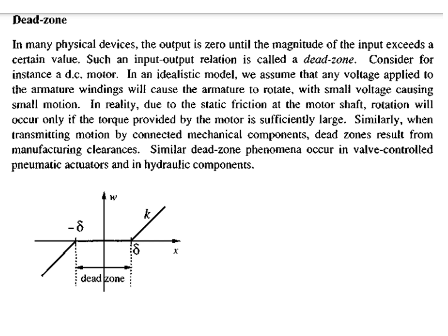Once it reaches the tolerance level, then it is going to increase according to the characteristics of the device. Say, for example, take the same PN junction diode and its VI characteristics. For a diode made of silicon, only after 0.7 volts does the current start to conduct. Similarly, if you take germanium, only after 0.3 volts does it start to conduct, in both the forward bias and reverse bias.